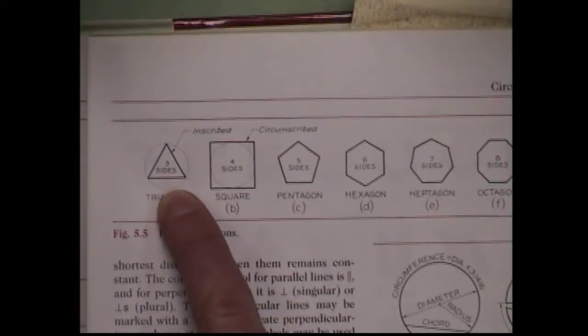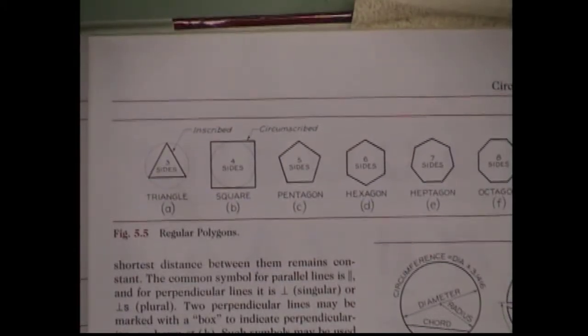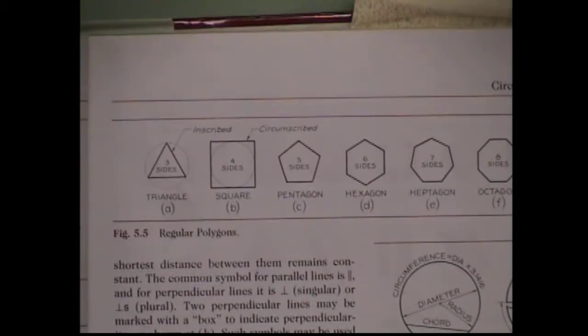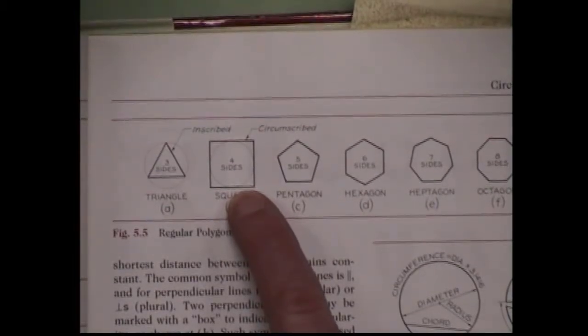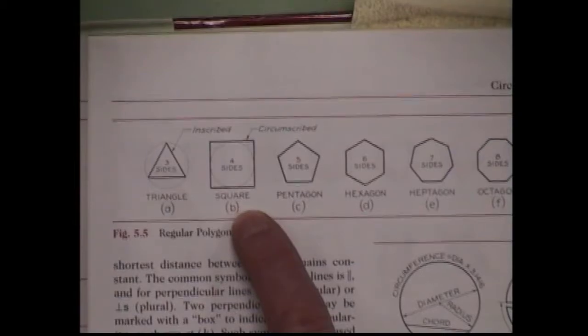Okay, every software that you're going to use is going to ask you, do you want to inscribe or circumscribe? You need to know the difference. Because if you choose the wrong one, you're not going to make it the correct size. And I have a couple drawings that purposely try to trick you because you have to make that choice and you have to make the right choice. So if it's inside the construction circle, we call that inscribe. If it's made on the outside of the construction circle, we call that circumscribe, like you see here in B.